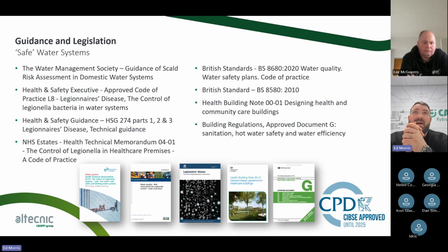NHS estates, the Health Technical Memorandum, HTM 04-01, the control of Legionella in healthcare premises, and that's a code of practice. There's British standards that sit around there, so BS 8680:2020, it's the water quality, water safety plans and code of practice. The British standard BS 8580:2010. The Health Building Note 00-01, that's designing health and community care buildings, so how we design safety into systems. And the building regulations Approved Document Part G, that's sanitation, hot water safety and water efficiency. So there is plenty of guidance out there, or codes of practice, shall we say, or standards which sit around the control of water within buildings.